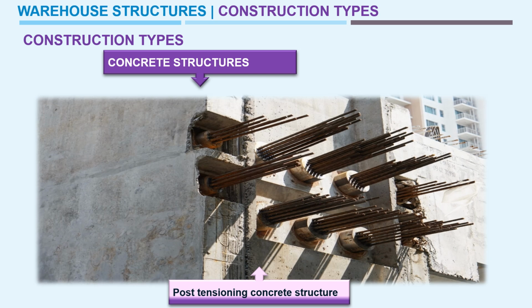But in the case of post-tensioning concrete, the structure is partially fabricated in the factory, and then brought to the site. For example, the column is cast at site, and the beam is factory made and brought to site, and both are assembled there. Once the columns and beams are assembled, the slab is laid over at site. Then the slab is installed with tendons, and the post-tensioning process happens at the project site for slabs. So these are the differences between post-tensioning and pre-tensioning.